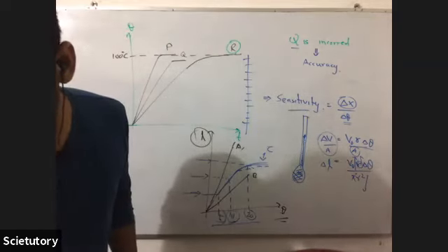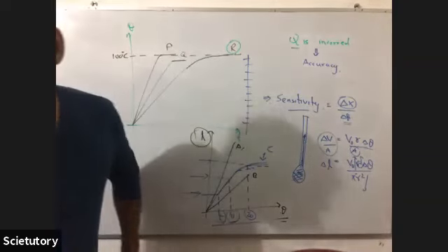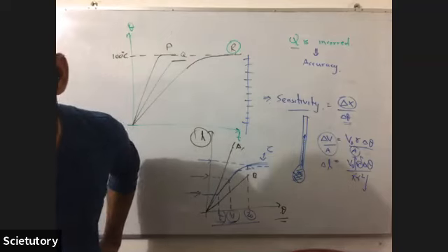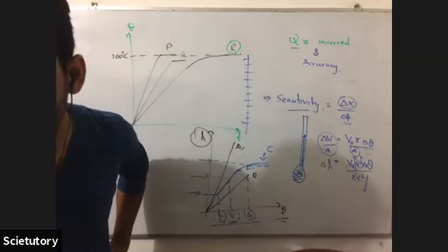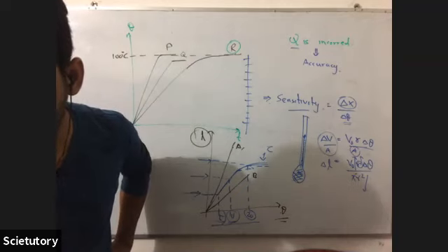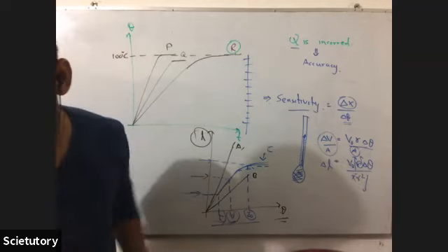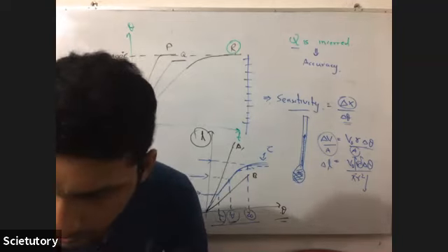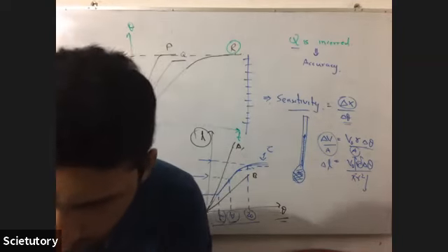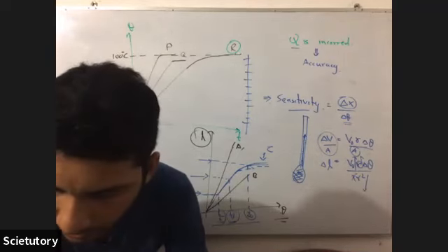The next question is a very interesting question. The breakdown voltage of the Zener diode in the circuit shown is 5 volts and RL is a suitable resistor. The capacitor C is first charged to 10 volts by closing the switch S1, and opening the switch S2. Subsequently, S1 is opened and S2 is closed. Consider the following statements made about the functioning of the circuit after S2 is closed.